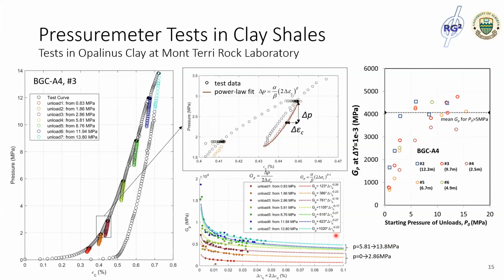And the dependence of this shear modulus on the pressuremeter loading was observed actually in all of our tests in this borehole. And this should be related to the stress-dependent behavior of the Opalinus Clay, particularly near the borehole wall, as I will further discuss in the later slides.